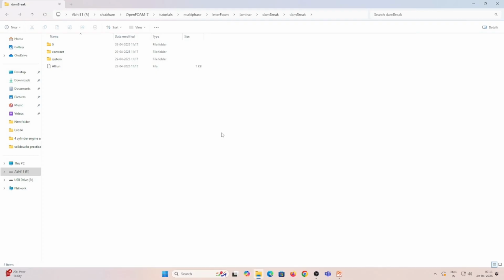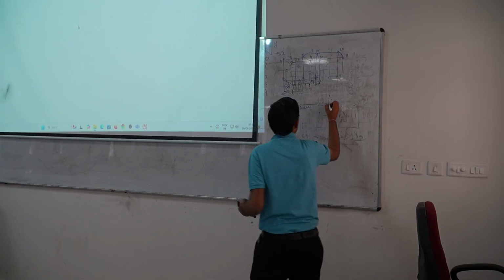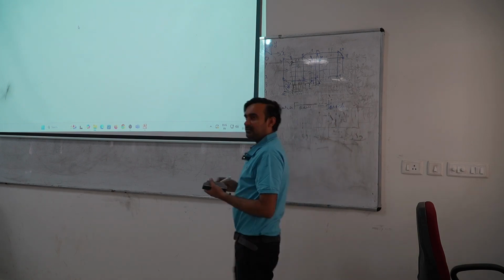PARA and F will be capital, FOAM, OAM will be small, hyphen touch, TOUCH. So what you need to write is paraFoam -touch. Have you run this command?